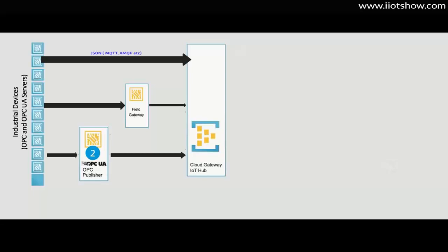on the network. So how it would work is that the publisher module would subscribe to the OPC UA servers, which in this case are the devices and sensors at the edge of the network, and the servers send data to the network, and the subscribe client, which is our publisher module, can receive the data and translate the OPC UA data to JSON format, right?